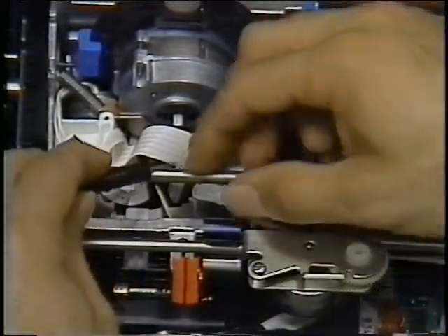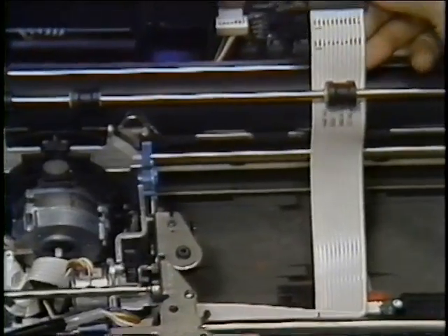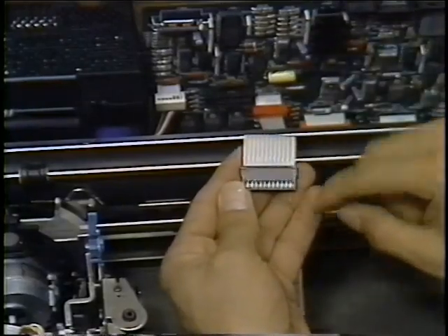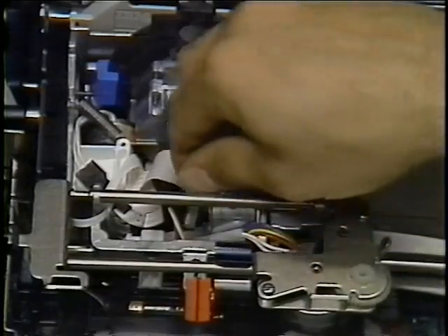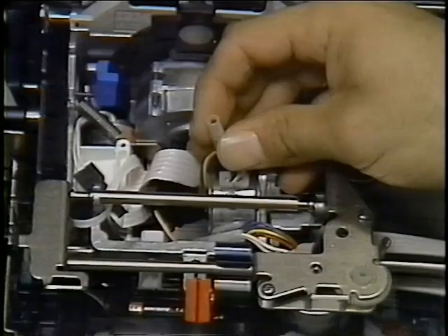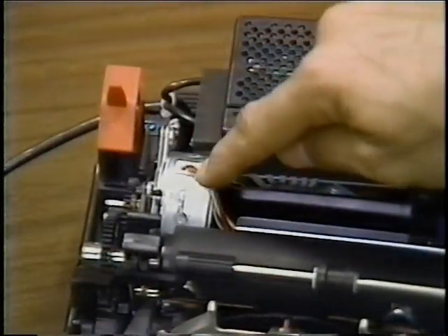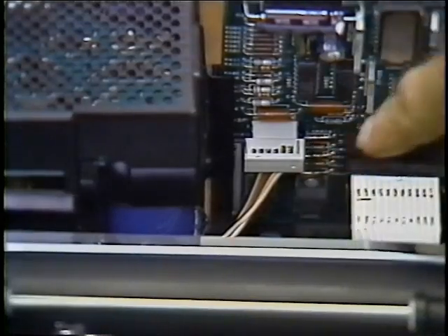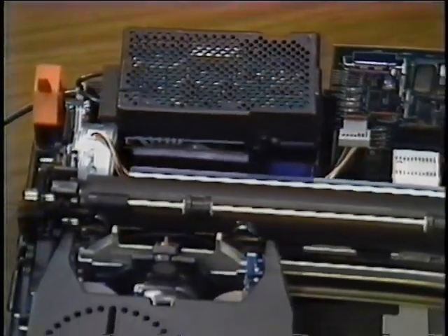In order to perform the ribbon feed motor resistance check, you will plug one of your meter leads in the test connector on the motor and measure the resistance from the test connector to each of the feed motor pins on the bottom side of the carrier cable connector. The resistance check on the ribbon lift motor is performed the same way as the ribbon feed motor resistance check. Remember that both ribbon motors have their own test connectors. The resistance check for the paper feed motor is performed in the same way as the transport motor resistance check. The procedures for performing all of the motor resistance checks are in the maintenance library. This concludes the motor resistance check section.